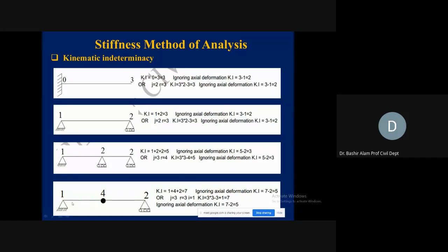So when it deflects, how is it going to deflect now? It is going to deflect here at this hinge, and from here it is going to come here. Now what will happen? This left side rotation is not going to be equal to the right side rotation. So at this hinge, we will have 2 different kinds of rotations. This is why we have 2 independent rotations.